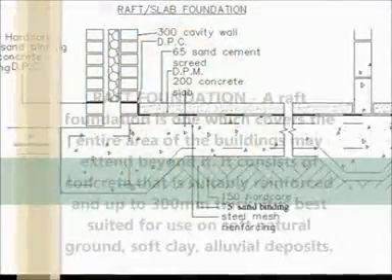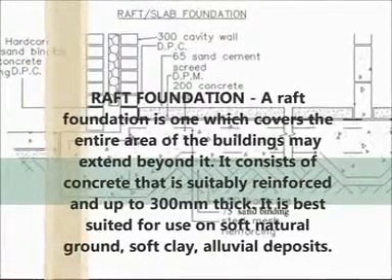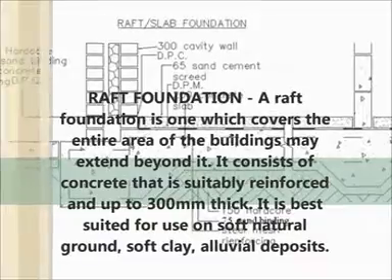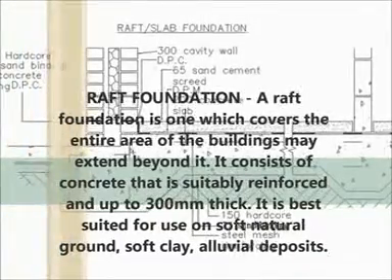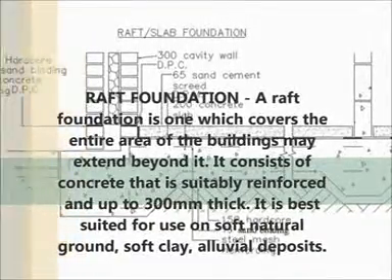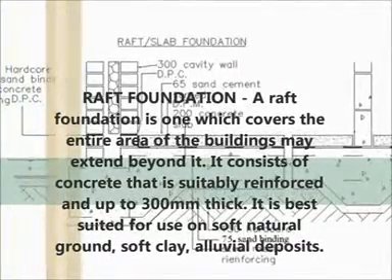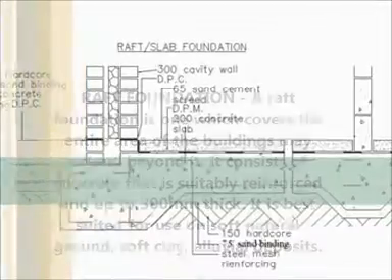Raft foundation. A raft foundation is one which covers the entire area of the building, and may extend beyond it. It consists of concrete that is suitably reinforced and up to 300 mm thick. It is best suited for use on soft natural ground, soft clay, and alluvial deposits.